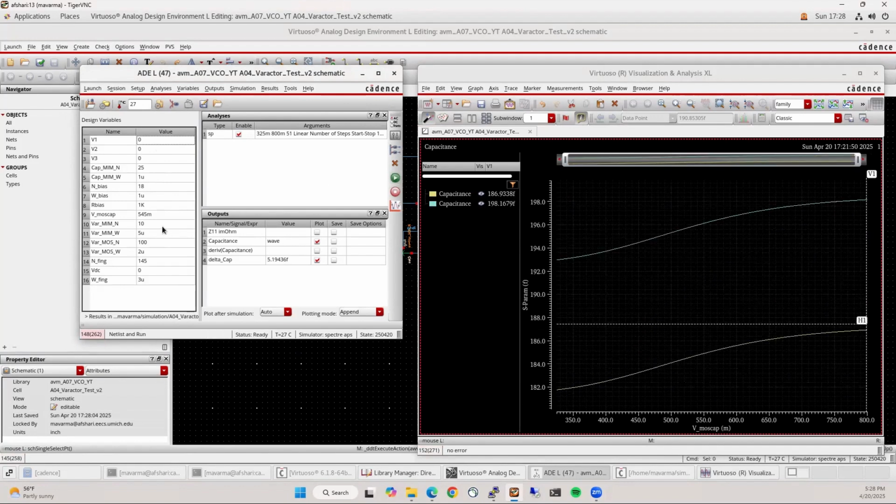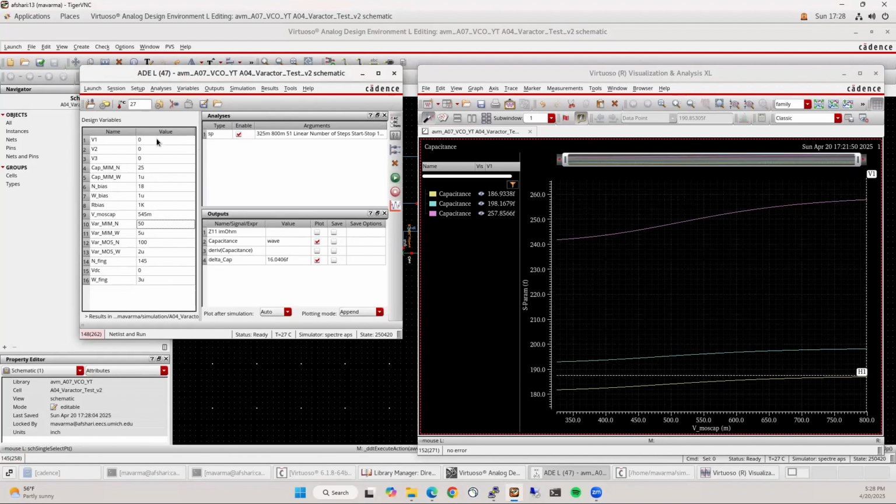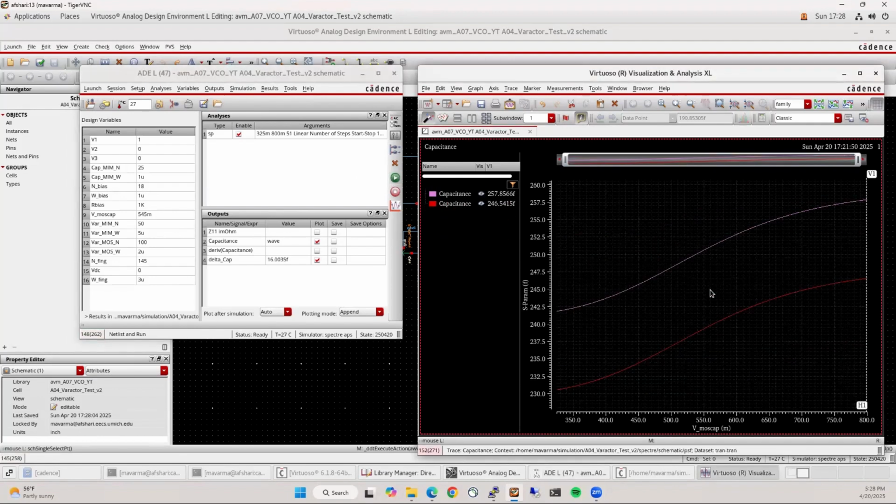Why is it bad? What if I make this 50? Okay, yeah, this is what I was looking for. All right, so now you see there's a good amount of overlap, right? So I just had some numbers off, but now I think it's correct. So quite a bit of overlap. So we have our 16 femtofarad there. And if I put a vertical line, that's around 11, right? So this is our CLSB is around 11 femto and times 1.5 is around 16 femto, right?